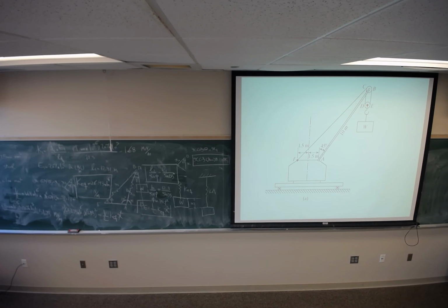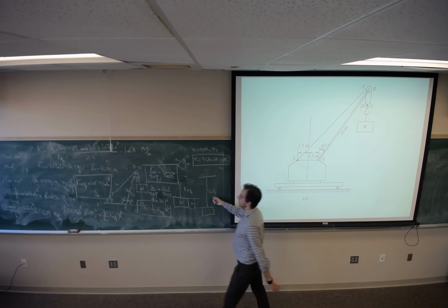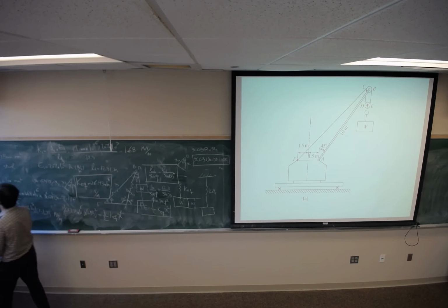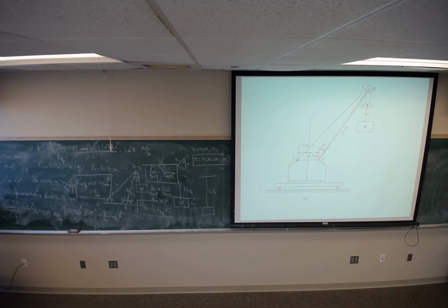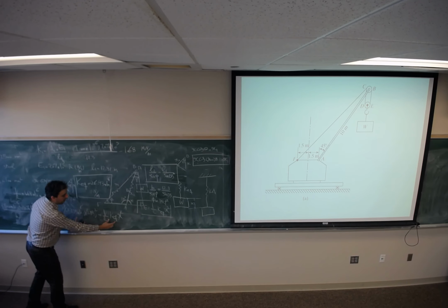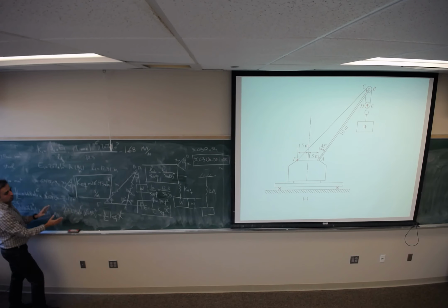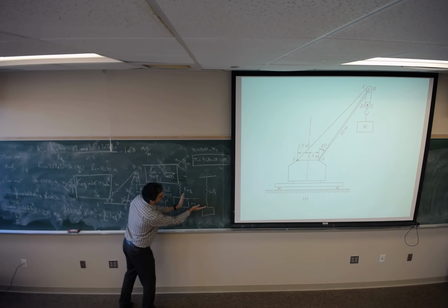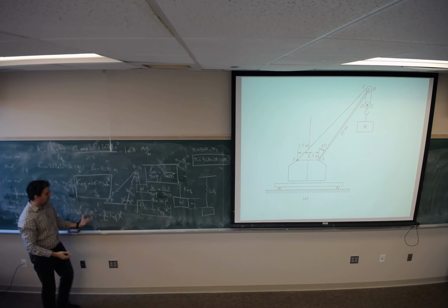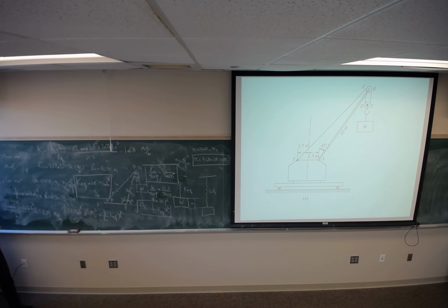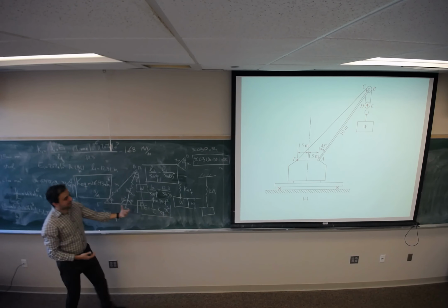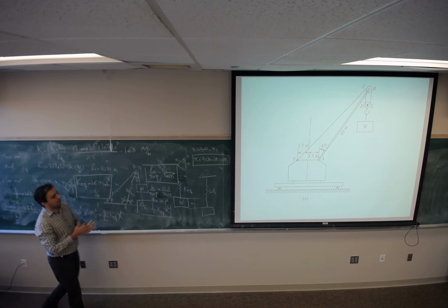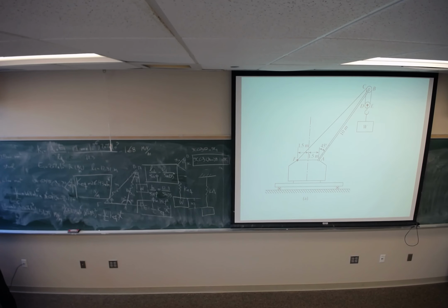If you remember, the spring is a means to store the potential energy. So we use the energy method by equating the potential energy of the original system and the equivalent. By setting up this equation, we could solve for equivalent stiffness. Mass is the means to represent the kinetic energy.